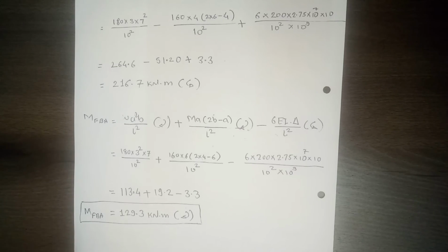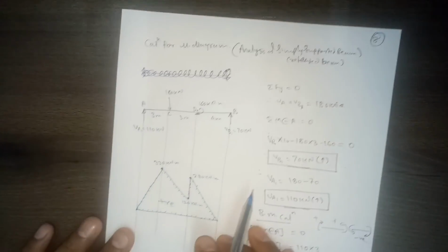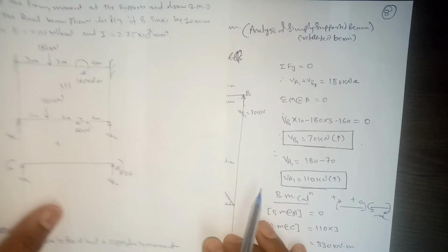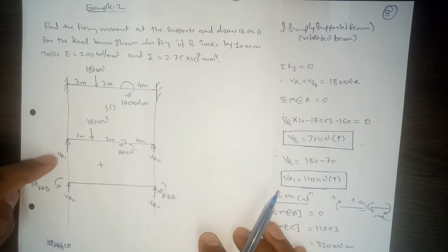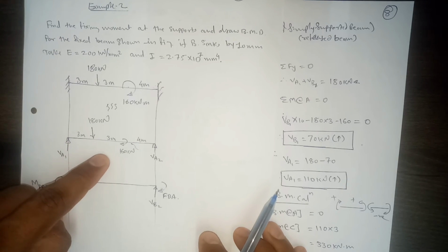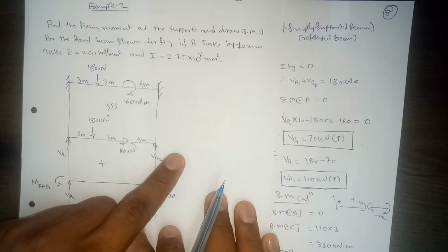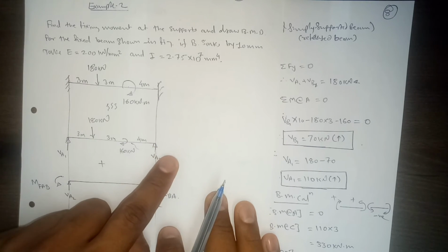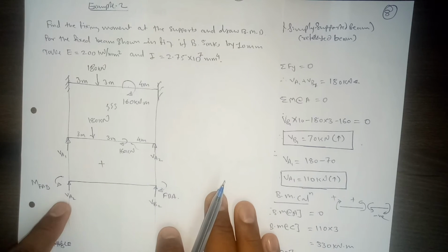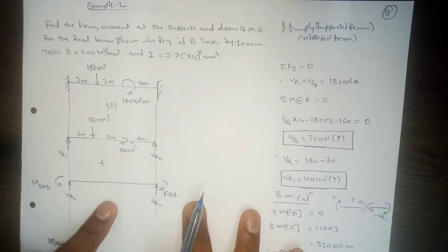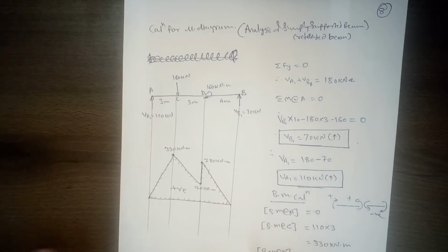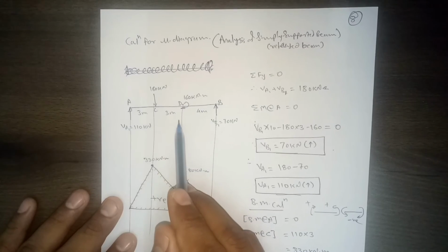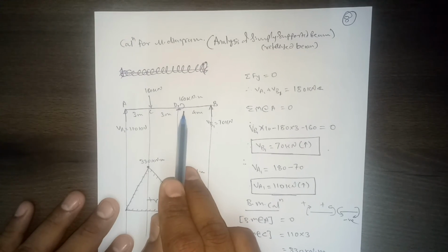Now we'll calculate the bending moment diagram. As I already told you, this given beam we can convert into two released beams. We'll apply the external load and calculate the bending moment diagram for this one, which we call the Mu diagram. Then for the fixed end moment, we'll plot another bending moment diagram, and that will be the Mu dash diagram. Finally we will overlap them. This is a simply supported beam with a point load and concentrated moment.